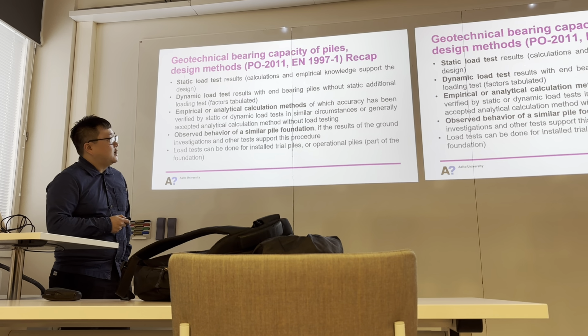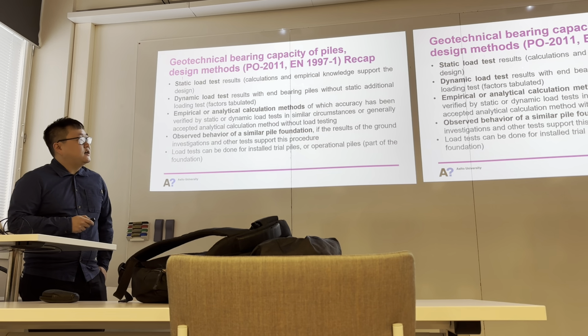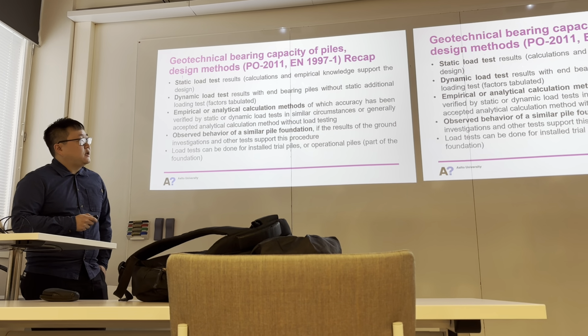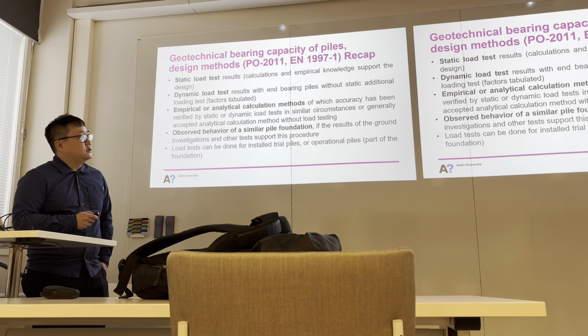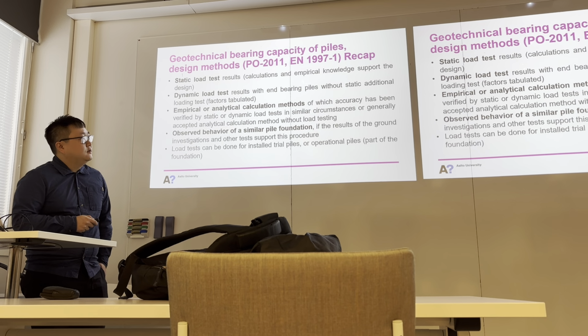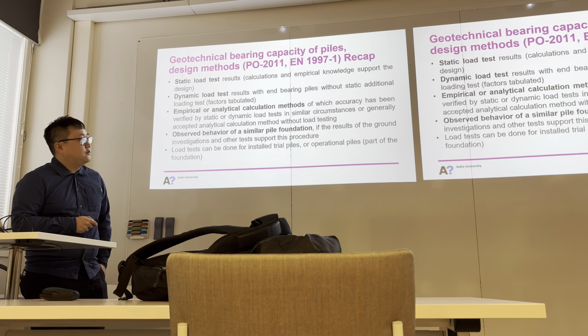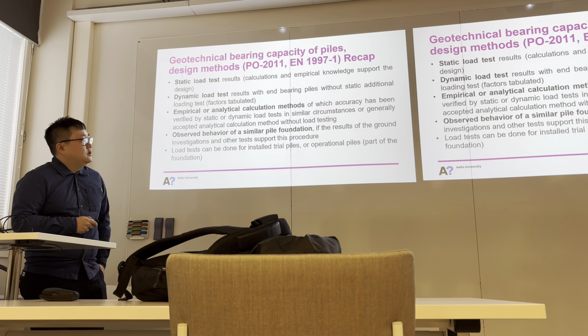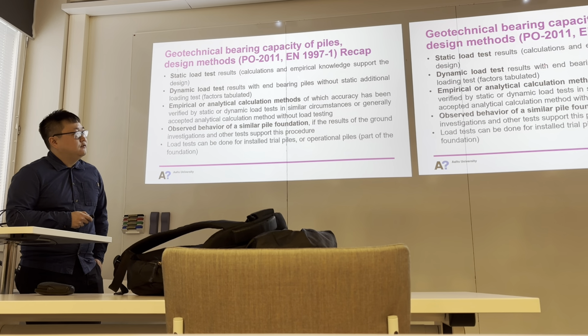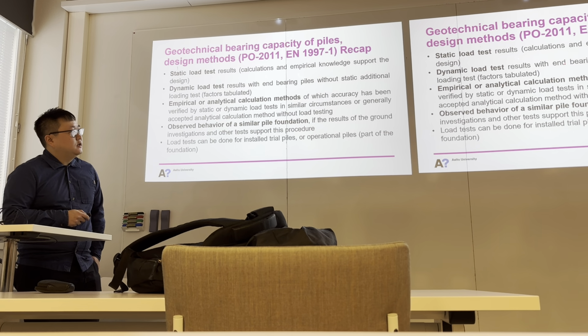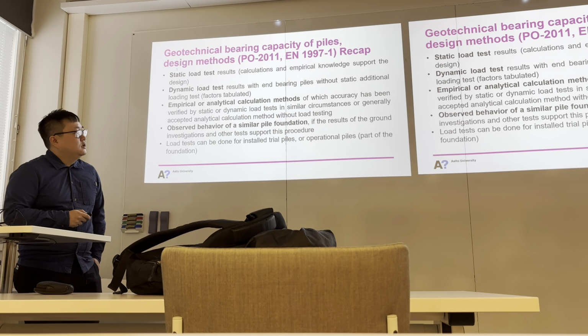Here I should highlight that when we do load testing, the test seldom stops until the failure of the pile. It's very different from the dynamic one. The second is the dynamic load testing results. This is very often used in Finland for the design of end-bearing piles. Both the static load test and dynamic load test are common methods for design.